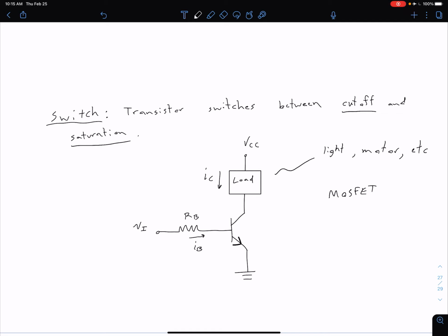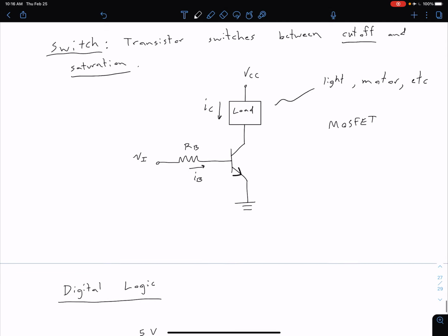We mentioned it briefly, but we didn't talk about the mechanisms: our BJT is going to have relatively high leakage currents compared to the MOSFET. On a single transistor scale, that's not so bad, but if we start using thousands, millions, and even billions of these things, that leakage current can really add up and become a significant power loss. So switches are an important application of our transistors.